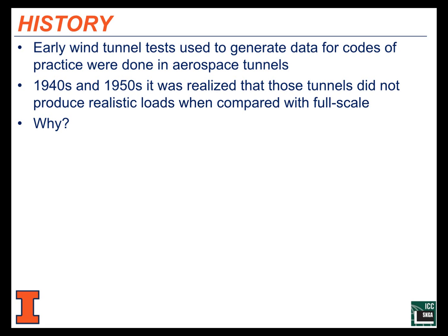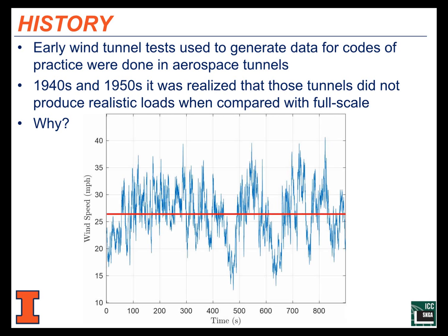The researcher on that project used a barometer to measure pressure, and what he found was that the barometer was fluctuating all over the place. If we look at an actual wind speed time history, you can imagine that it's fairly related to the loading as well, in that there are quite a bit of fluctuations in the data. This is a 15-minute record of wind speed, and you can imagine the fluctuations in loading would look similar to that.